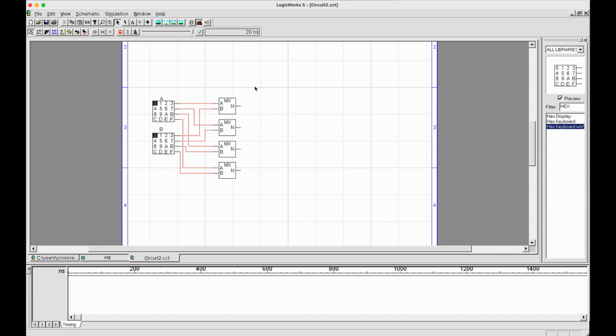When you're doing this kind of connection, sometimes it gets very confusing, which is why you can use something called a bus to help you mitigate this problem. Now, a bus essentially just gets rid of all of these wires and carries values on a single thick wire, like this over here. A single bus can carry as many digits as you want. And in our particular case, we'll be carrying 4 bits of digits from one location to another.